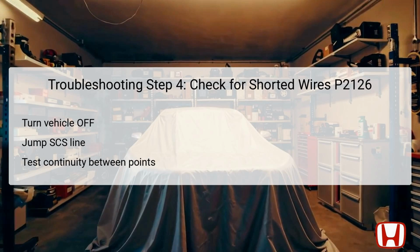It's now crucial to check for continuity between test points located on the APP sensor 6P connector and body ground. This procedure verifies whether the APP sensor's wiring experiences a short circuit. If continuity is present, it indicates a short in the APS2 wire, requiring repairs.